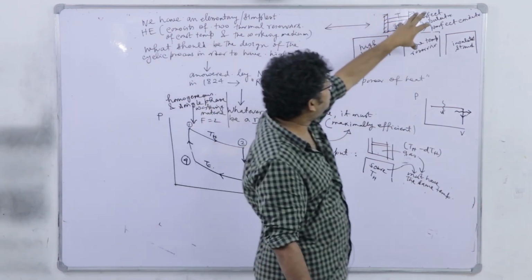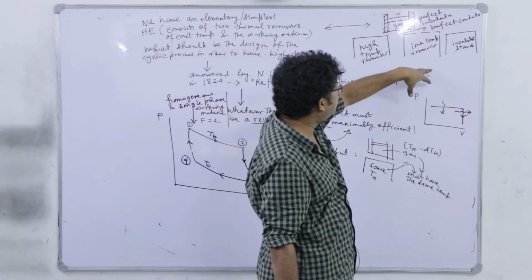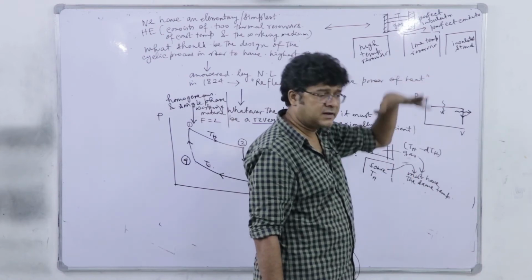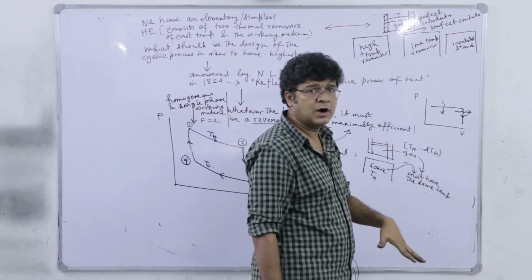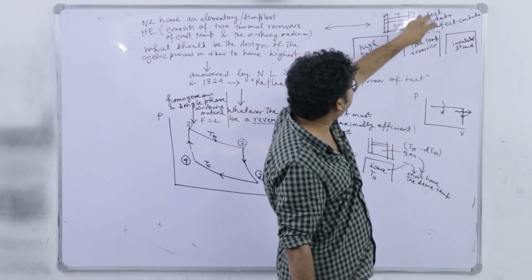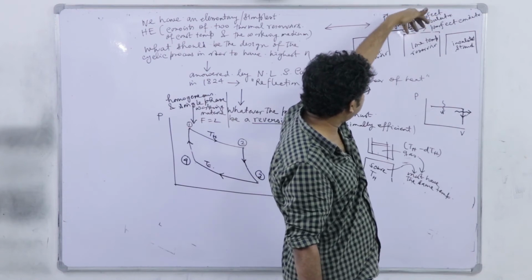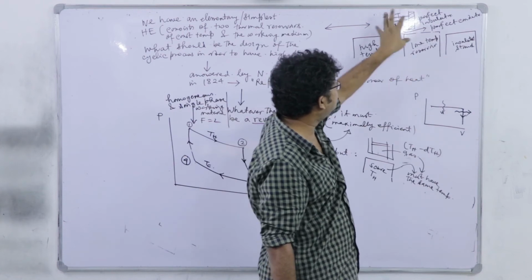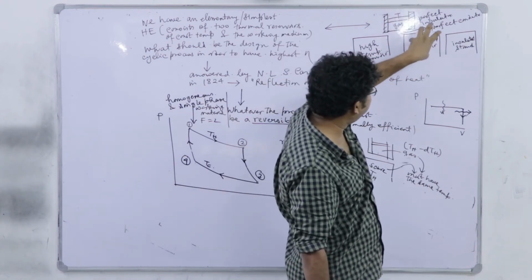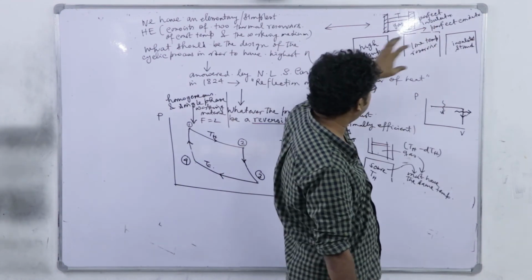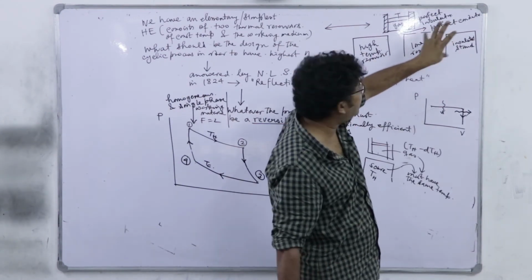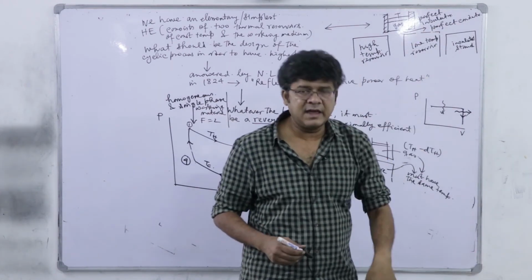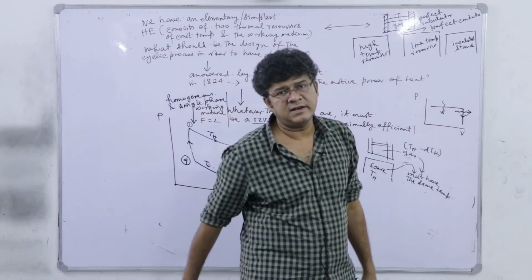So, once it has rejected the heat to this low temperature reservoir, we are actually compressing. How will it reject? We are compressing it. We have to do work on that, right. So we will put it here, we will do some external work, and the heat will be rejected. So it is an isothermal heat rejection step, and after that it will continue to a fixed final point 4, which is to be pre-calculated. Once this point 4 is reached, we will again put it on the insulated stand, again do some work such that the initial state is regained.